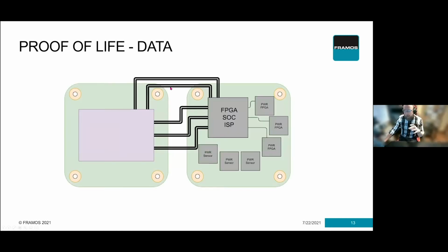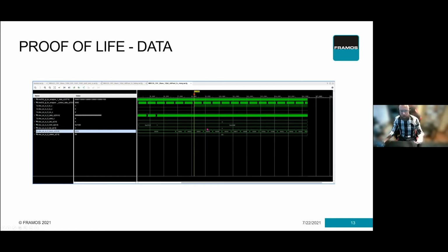But if we have a known good configuration going into that sensor, we can then look at various aspects of the connections to our FPGA to see if the data is there. That doesn't mean we have to look at an image level. We don't have to say, hey, I can't see an image. What you can do is set a certain pattern of data onto my data lines, and I'm also going to look at my clock line, and then decide whether I can see it or not.